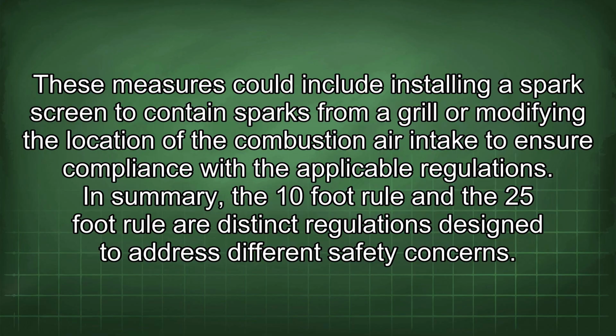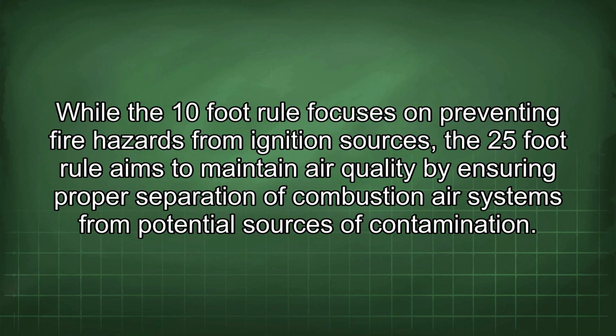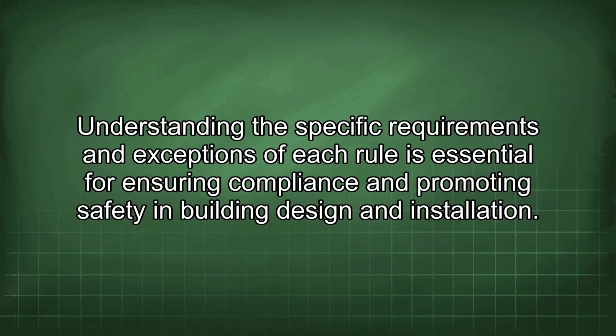In summary, the 10-foot rule and the 25-foot rule are distinct regulations designed to address different safety concerns. While the 10-foot rule focuses on preventing fire hazards from ignition sources, the 25-foot rule aims to maintain air quality by ensuring proper separation of combustion air systems from potential sources of contamination. Understanding the specific requirements and exceptions of each rule is essential for ensuring compliance and promoting safety in building design and installation.